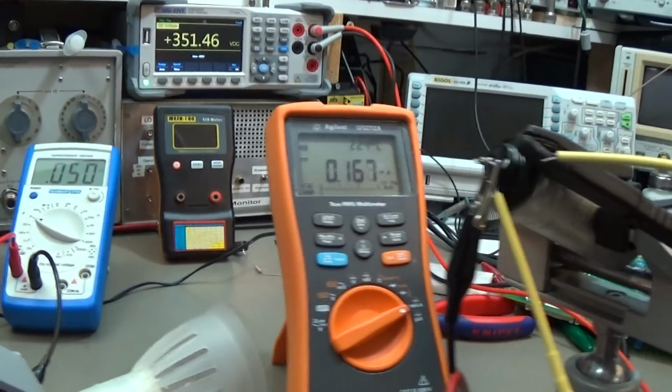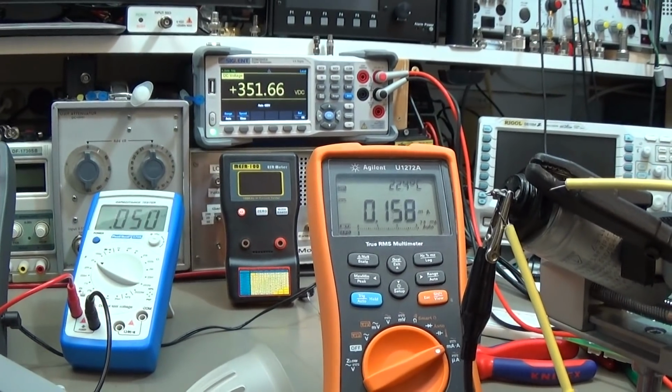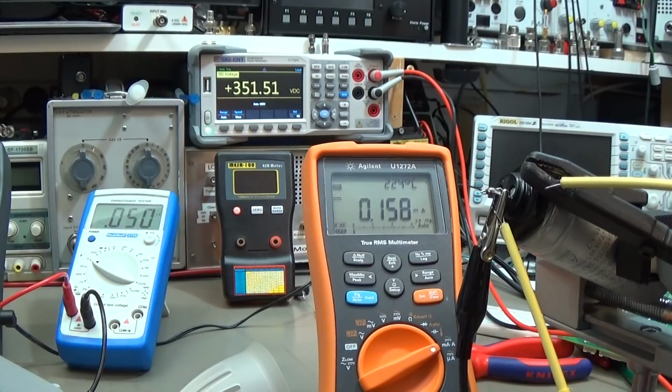And by the way, while we are talking, you see our value here dropped down to a level where we are now within the spec of a very new capacitor. So once again, 350 volt, 47 microfarad. We would expect with a modern type 164 microamps, and what you see, we are reading here 157 microamps. That is telling us that our old capacitor is already in spec for a new one.